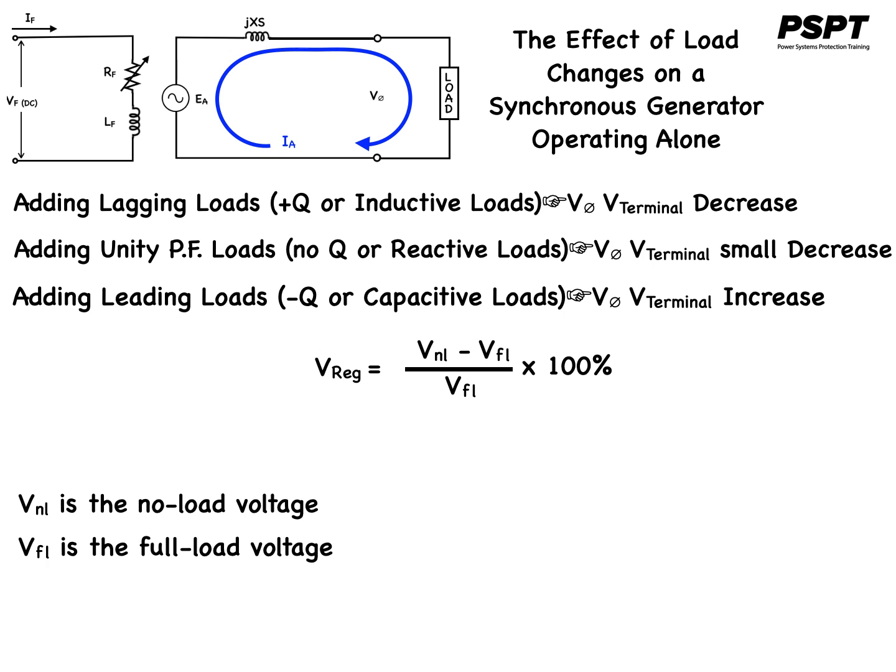Normally, it is desirable to keep the voltage supplied to the load constant, even though the load itself varies. How can terminal voltage variations be corrected? The obvious approach is to vary the magnitude of EA to compensate for changes in the load.